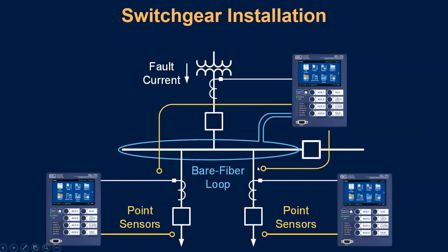And if I see an overcurrent condition here through these bus CTs, and if I see a flash of light on any one of the sensors connected to this relay, you can see based on where I've put them and where I've covered, we know that if any of these receive a flash of light, those are in the zone of protection of the main breaker. And so we would couple that current and this light to determine that we should trip this breaker as quickly as possible.